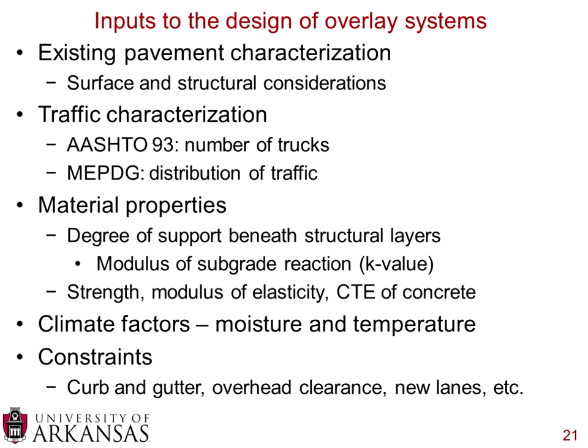And there can be some other things in there, but at the end of the day, the aggregates and the cement are the most important. And the CTE is how much that pavement expands and contracts as the temperature goes up and down. And you want to make sure that the CTE of the paste, which is the hydrated cement, is similar to the CTE of the aggregate that you're using.